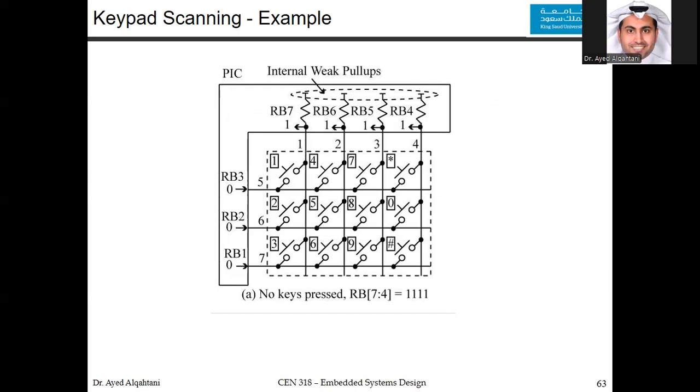The way we connect it, we can change the TRIS value the way we want. So at this point, we make RB1, 2, and 3 output from the PIC24. If there's connection between any two systems, if it is an output from system 1, it will be an input to system 2. So when we configure TRIS, always your center of attention should be the PIC24. Is it an output from the PIC24 or input to the PIC24?